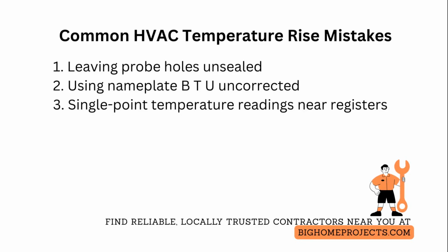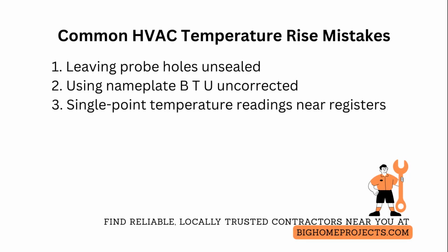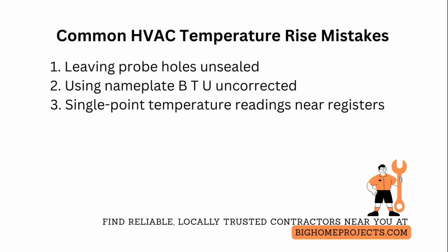restored performance. One of the common mistakes is using nameplate BTU without correcting for measured efficiency, producing incorrect CFM estimates. Remedy that by performing a combustion efficiency test or using manufacturer-rated net output and documenting the correction factor used.